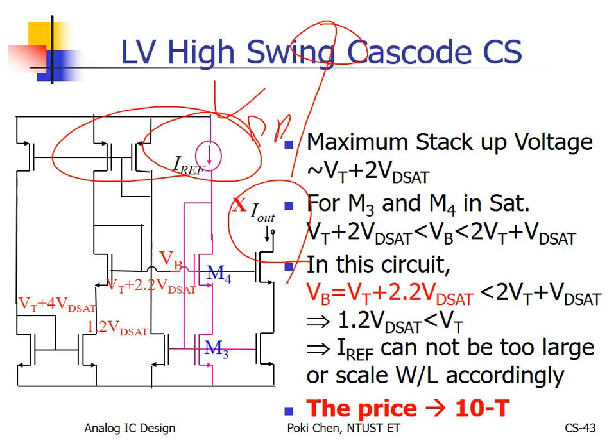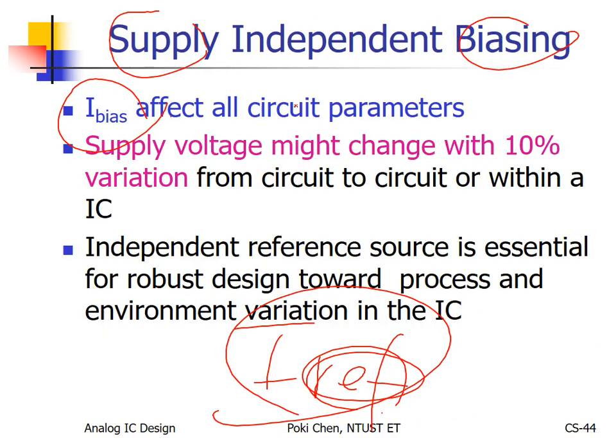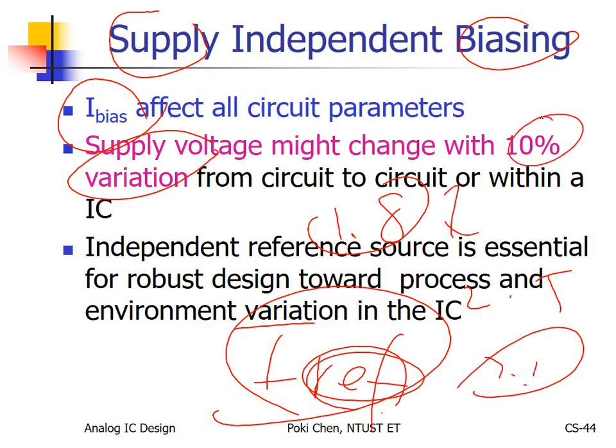I don't change my value, my amplitude, under any kind of situation. I mean temperature change, I mean supply voltage change. No. I need to stand still. I don't change myself. So how to generate a supply independent bias? It is really important for some applications, especially for commercial chips. If they tell you it can operate under 1.5, 1.8, 2.5, 3.3, usually the tolerance is positive, negative 10%.